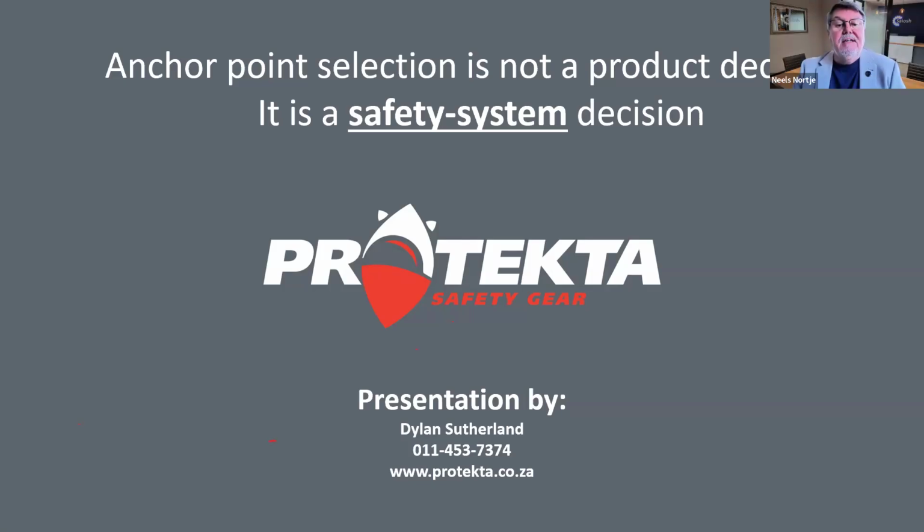Thanks for that. Stefan asked, is there a calculation to determine the amount of kilonewtons or the weight that the system has to be tested against? I think you covered that. For example, single user weight, 100 kilogram. I think that was covered quite well. I don't know if you want to add to that. Yeah, we saw that. The standards have their certification. I just made it practical as to what it can look like. But usually you're working anywhere from 12 kilonewtons to 22 kilonewtons. Right.